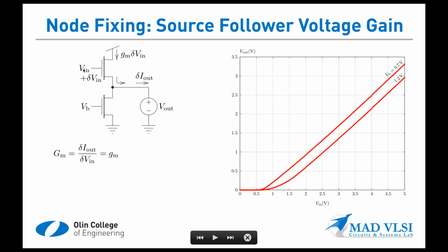So here we've got the input voltage coming into the gate of our source follower transistor, and we fix the output voltage at whatever the quiescent output voltage was going to be. It's a bit below, roughly a VB below Vn. But that input voltage change is a gate voltage change, and that's going to give rise to a change in the current flowing through our source follower transistor of the little gm of the transistor, the transconductance gain, that's dI_sat/dVg, times the input voltage change.